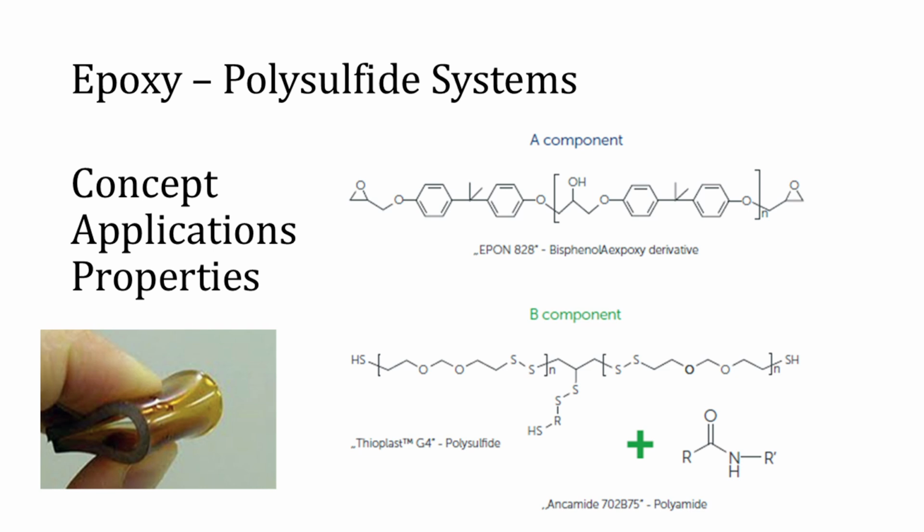These intumescent polysulfide sealants form a strong carbon-rich foam when exposed to fire, acting as a barrier to heat and preventing the spread of flames. Beyond fire protection, these sealants retain all the desired features of standard polysulfide-based building sealants: excellent flexibility across a wide temperature range, resistance to weathering, chemicals, solvents, and water, strong adhesion to various substrates, ease of application, and non-staining behavior